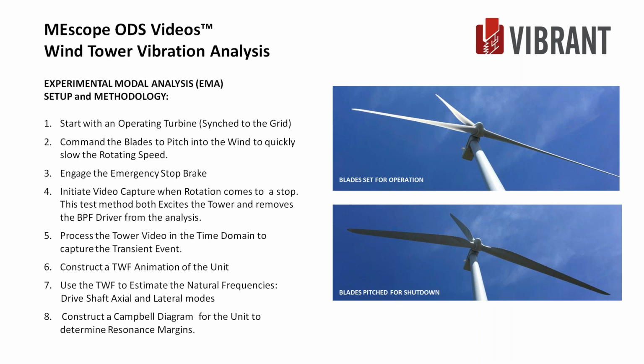So once it's stopped, the blades will pulsate a little bit, but you lose that blade pass frequency and that turning speed response, and you have basically a quiet, non-operating system that you just hit with a hammer, and the hammer is the wind, or actually removing the wind. And now you have a nice sinusoid of the tower.